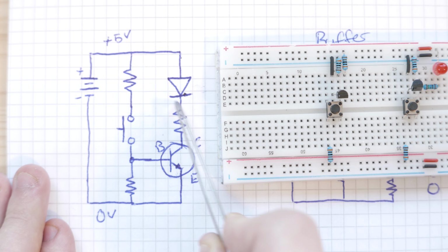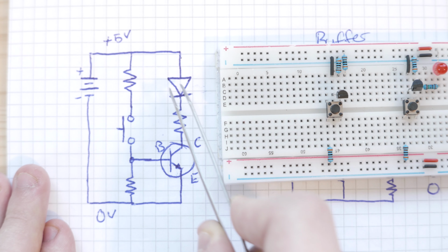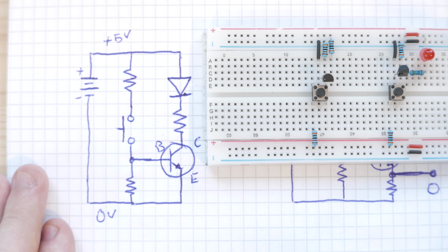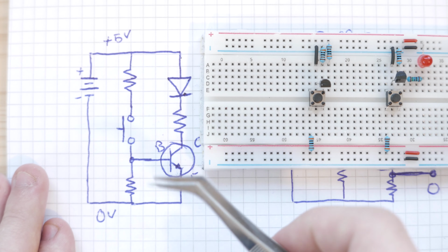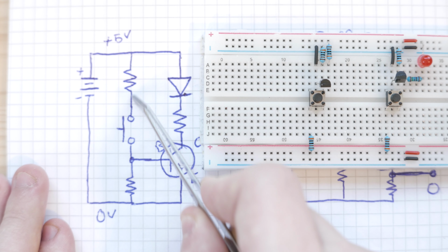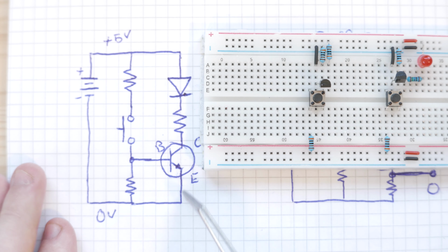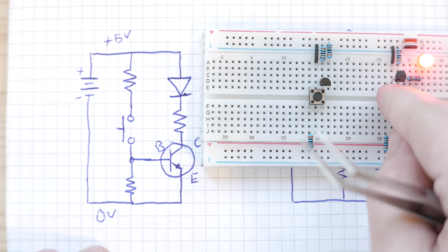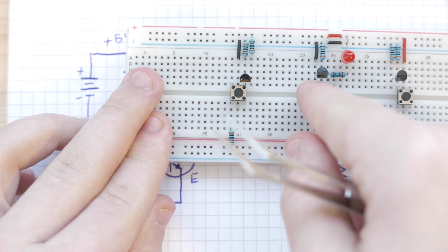And you'll see that here I have an LED hooked up. Now I've just drawn this as a diode, but this is actually the LED that is here. And you'll also see that I have a resistor in series with it, and this is just a 150 ohm resistor to give about 20 milliamps of current through this LED, which is the max rating, by the way, so it's going to be pretty bright. But as you'll see, when I click the switch and close the circuit, current flows through the transistor, and turns it on, and allows current to flow through the LED to ground. And as you'll see, that lights up the LED.